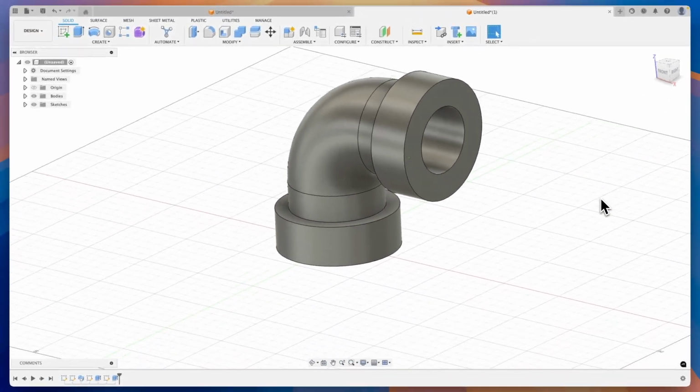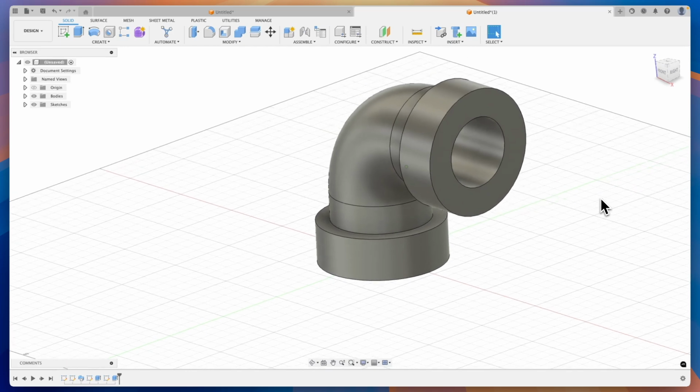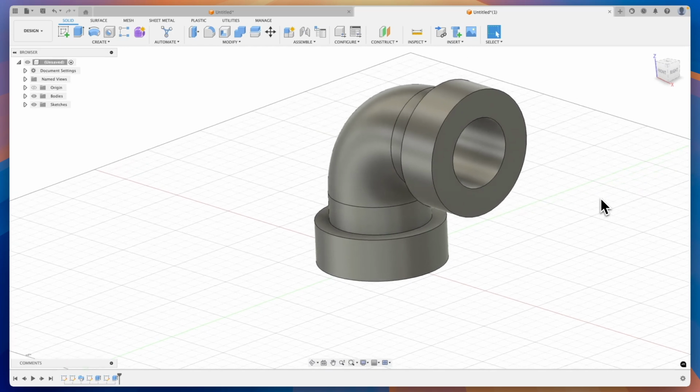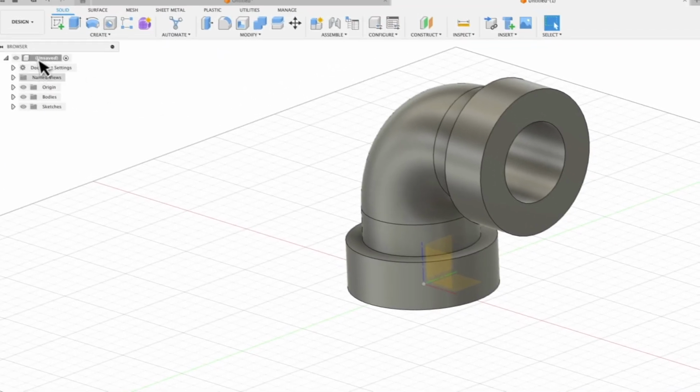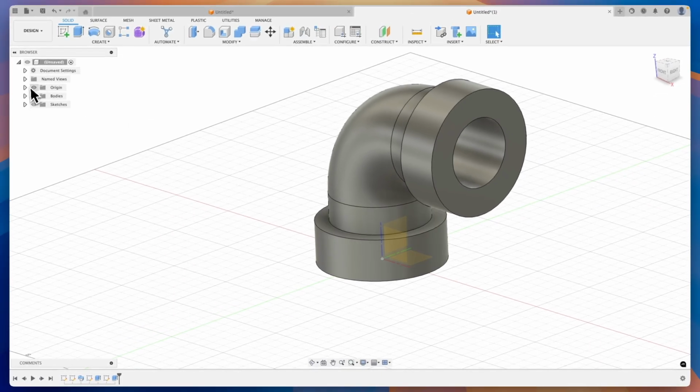Now I would like to divide this solid into two parts. In this case, I will use the XZ plane for the division, but actually, when it comes to dividing a solid, we can do it arbitrarily. We just need to create some cutting geometry. In this case, I will use the XZ plane as the cutting geometry. I will turn on the visibility of the coordinate systems and planes so that they are visible in the workspace. Here we simply click on this eye icon to ensure it is checked so we can see these planes in the workspace.